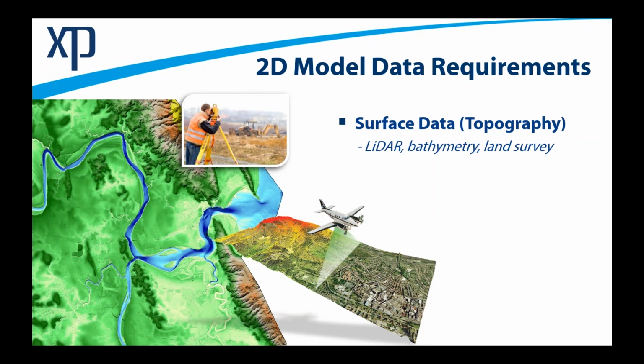So if this is the case, then it's also worthwhile contacting your port authorities and transport departments to try and get bathymetry data sets, which can easily be merged into an XP model. In addition, also contact your key overland transport departments, so your departments of rail and Main Roads, to try and get their land survey data sets for roads and rail corridors. Very useful data sets, if nothing else, to benchmark that the LiDAR is correct.